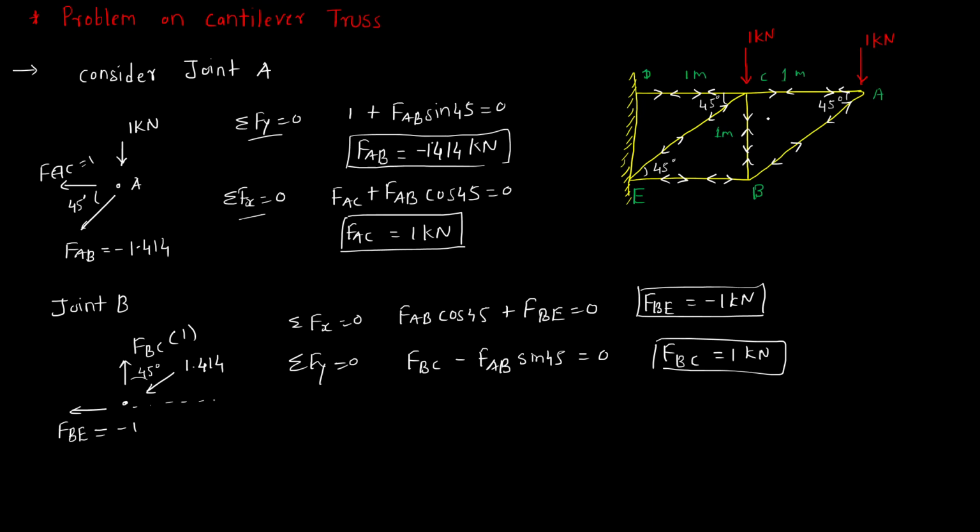Okay, so now you can see that this member is in tension, this is also in tension, this is in compression, compression, tension and compression. So about the nature of forces we can directly say it by looking at this diagram and the values of forces that we have already calculated. Now we'll summarize all these results here.